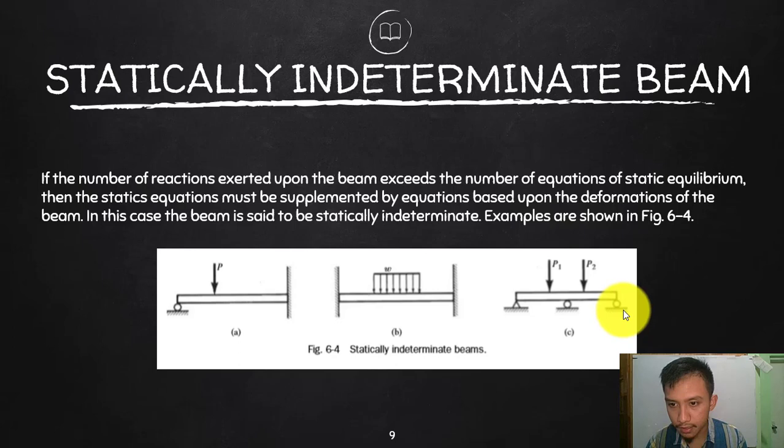And in here, look at that, 3 simple supports. So actually 1, 2, 3: 3 vertical supports, 3 vertical reaction unknowns. However, there will be a 4th here, which is your horizontal. But even if that is 0, that will also neglect the summation of horizontal forces, which will reduce our equilibrium equations to 2, only summation of moment and summation of vertical, and compare that to the 3 unknowns.